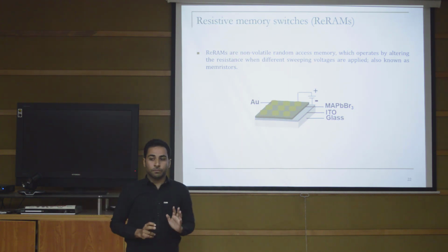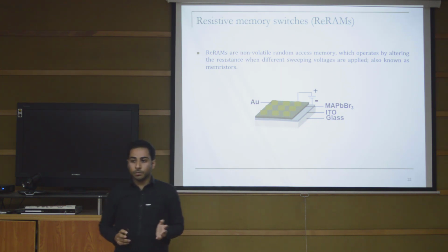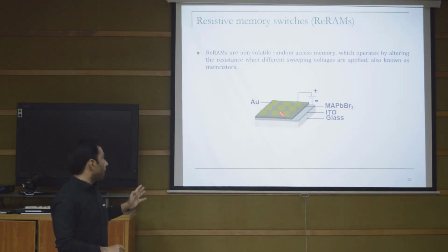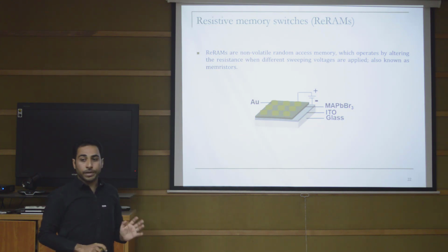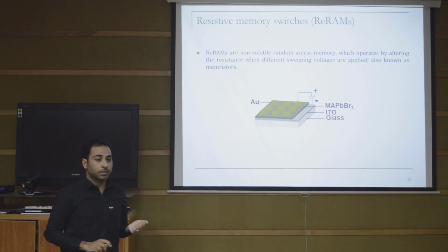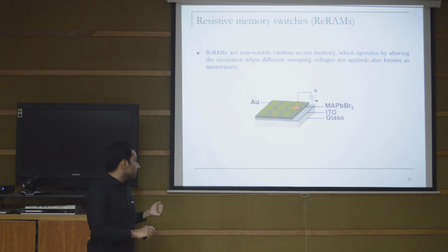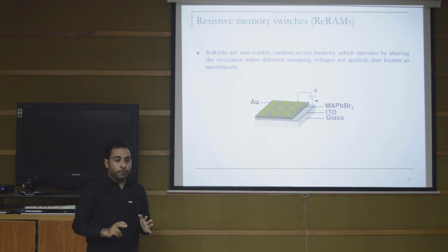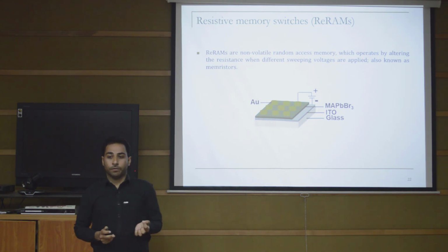This device is very simple, but I don't know whether you have the characterization tools for this or not. The device fabrication is very simple. You just have to deposit the perovskite film on the ITO glass, and then deposit some gold electrodes. This process is a bit intricate, but we have tried even a gold wire for this.